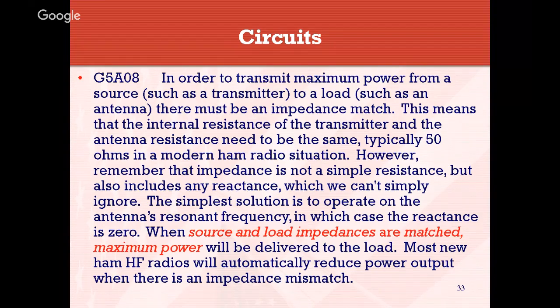But if you remember back from your tech class, a little bit about how to calculate the resonant frequency of an antenna. If you're doing just a simple wire dipole, you calculate the length of that antenna based on the frequency or range of frequencies you want to operate.